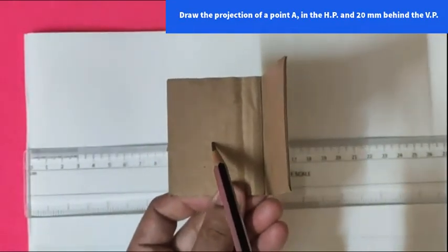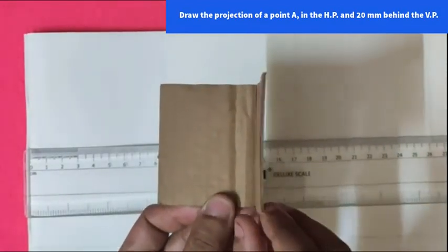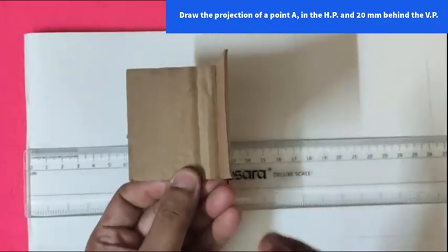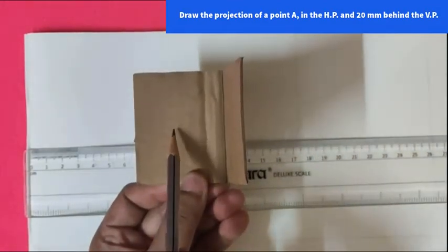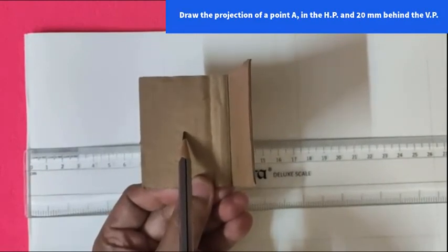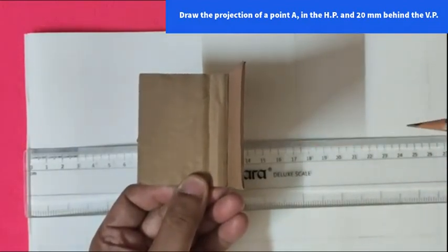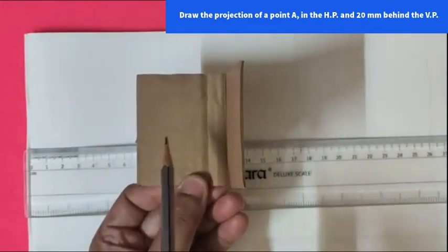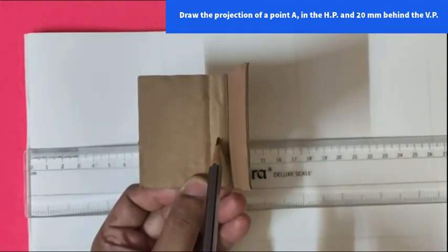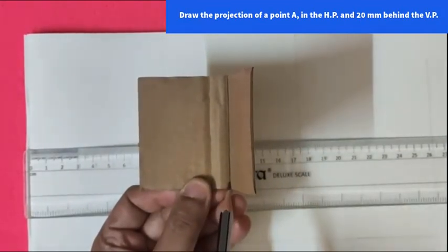So here in the first question, it says the point is in the HP, and it is 20 mm behind the VP. So behind the VP, that means this is the second quadrant. So first, the point is in the HP. When we see from this side, the front view, then the point in the HP will be projected where? In this XY line.